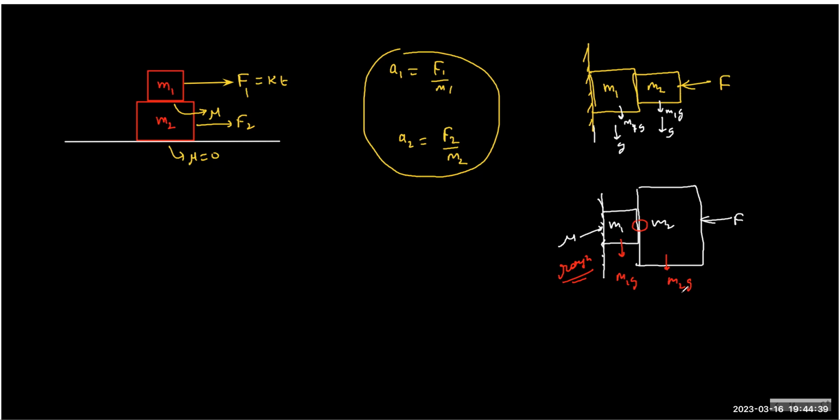And because of this reason, here the friction in this part will be extreme. I mean, of course, zero. If this is zero, then no friction will develop at all between the blocks, and the blocks will just move in free fall. So here A1 equals A2 equals g. That's the answer. But the moment you introduce the friction, and why I am emphasizing this problem, because I have seen students struggling with this kind of problem.